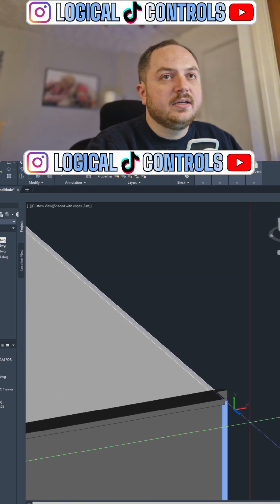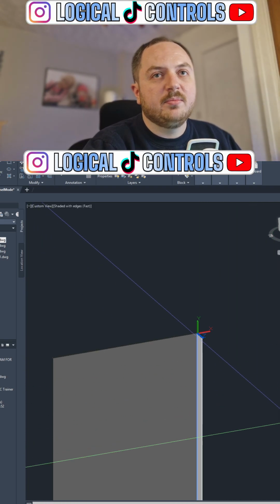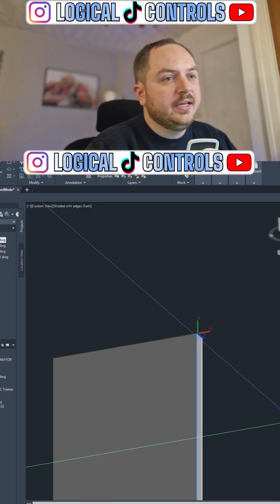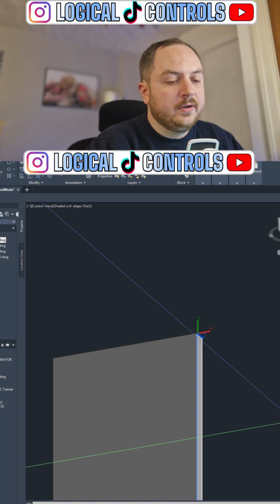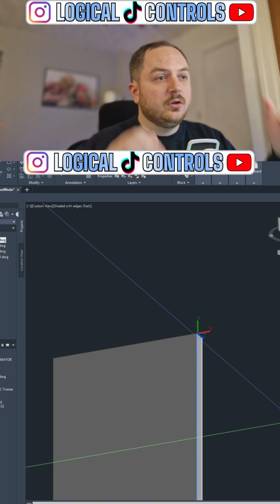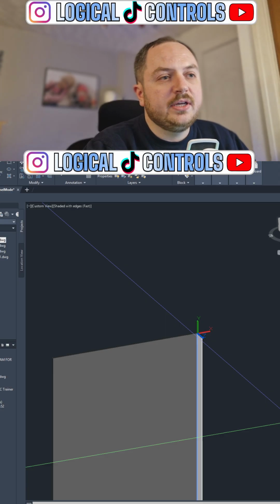If you've ever had a large piece of thin material, whether it be plastic or whatever, it's very bendy, it's very twisty. There's no strength to it whatsoever. If you put return folds on all the edges, you get a lot more strength out of it. It's not easy for that material to bend or anything.